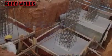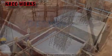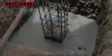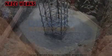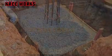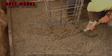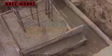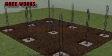Shuttering removal. The formwork removal procedure should be supervised by the engineer to ensure the quality of hardened concrete and structural member. That is, it should be free from or have minimum casting defects such as honeycombing, size and shape defects, etc. These defects in concrete influence the strength and stability of structure. Thus, immediate repair works can be done or the members can be rejected.